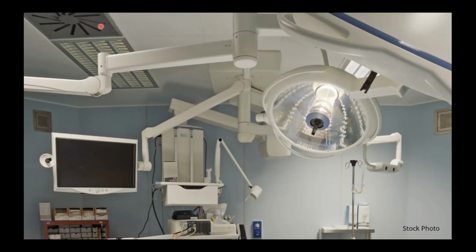I also see return grills that look like they're high on the wall on each side. So we can't quite see the floor. So if they have low return grills on the floor, that's fine. But if this is the only location of return grills in a space, that is not ASHRAE 170 compliant. ASHRAE 170 dictates return grills to be low on the floor, 8 inches above the floor, ideally.